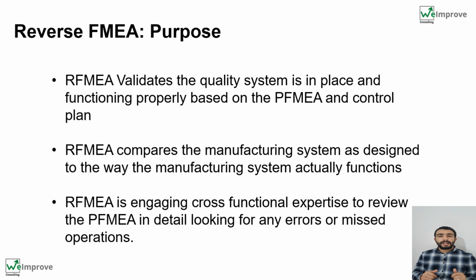So when you are making the reverse FMEA, it means that when you go to your shop floor to check exactly what has happened, sometimes you recognize that there is some new process, new operations, new steps, new sub-steps, or a missing process, and so on. Then when you compare with the reverse FMEA, sometimes you find out that you are missing this new process or this new operation. Then you have to start to think about what we have to do, what the risks behind it are, and so on. So this is exactly the purpose of the reverse FMEA.